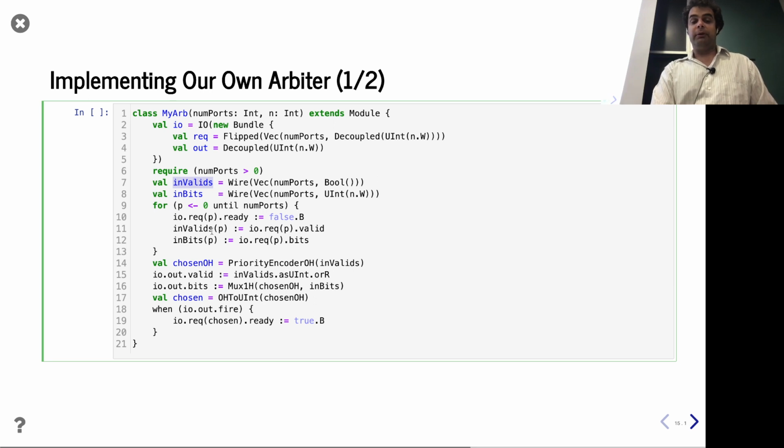So really what's going to happen when this program runs is that we're going to end up with a graph of Chisel components that happens to have a Vec of size 4. And for each one of those elements in that Vec, they're all going to be connected. So that when this function is done, you're going to have a Chisel graph that corresponds to the design we want. It's going to have a Vec of 4 ports here, a Vec of 4 ports there. So these for loops no longer exist, right? Those are just executing to build this graph up, but now the graph exists, they don't exist, and then this graph by the internals of Chisel is going to get turned into hardware. So really, our job is just to instantiate things and connect them. And so the for loop is not going to be in hardware. The for loop is going to be in the Scala program that's generating the hardware.